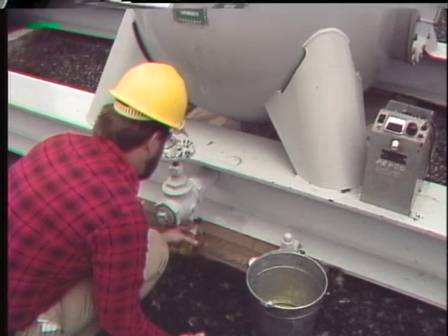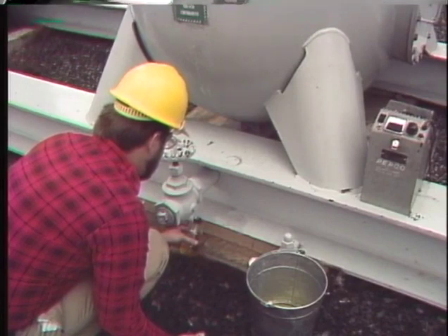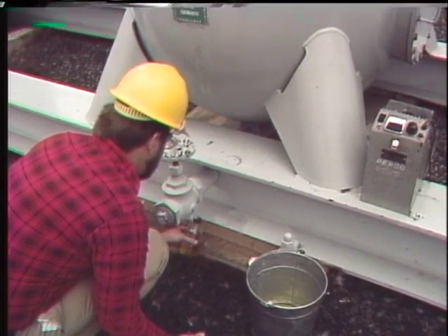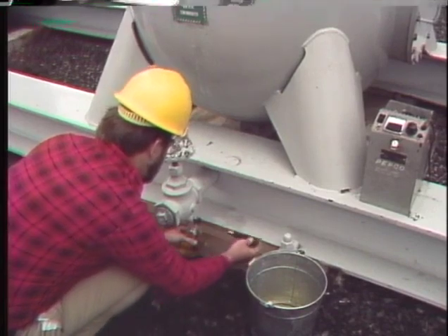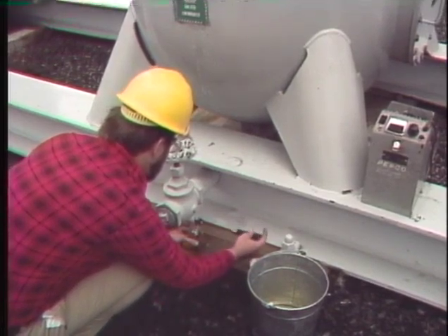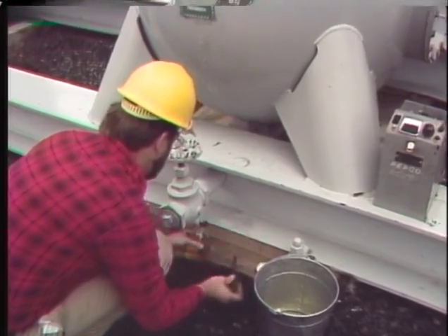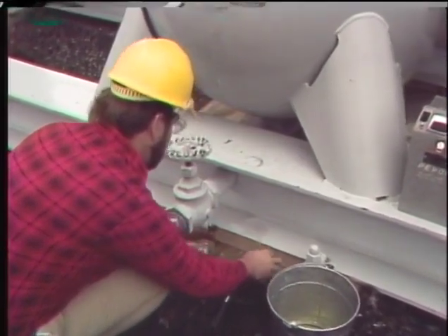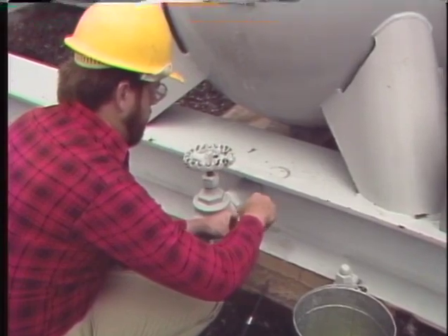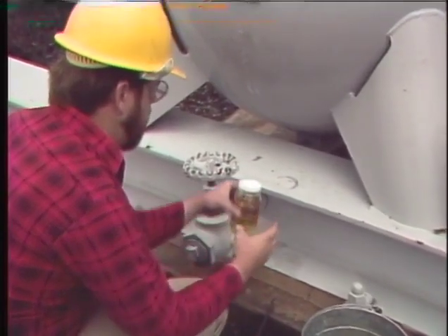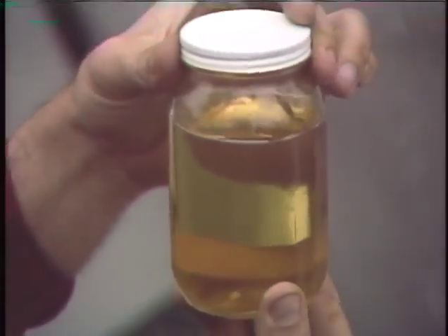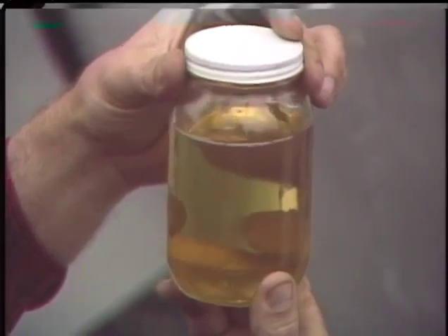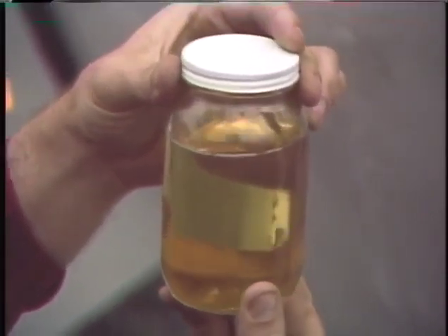To test the oil, a sample is drawn through a sampling valve at the bottom of the breaker. Several gallons are drawn off to purge the pipe and make sure the sample is from inside the breaker. If water comes out when the valve is opened, it indicates that there is a leak in the breaker that is allowing moisture into the tank. The dielectric strength of the oil will probably be very low. Metal or wood particles in the oil are a sign of internal damage, something to keep in mind when you go inside the breaker to inspect the internal components.